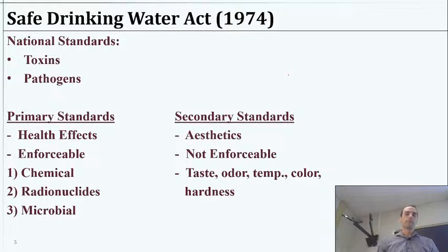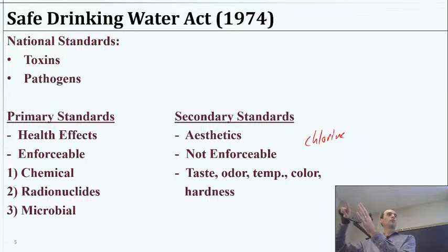So that would fall into taste and odor. Chlorine would be an example there, even though one of the standards we hold is we say we have to chlorinate and have to have some residual, right? So one thing we might do is take a look at a system that's chlorinating and look at the chlorine levels from the water storage through the distribution and see the chlorine decay across that distance. Something we looked at briefly on my last trip there. They had some questions like, is this too much? So we were able to go through and check and give some data and all that.